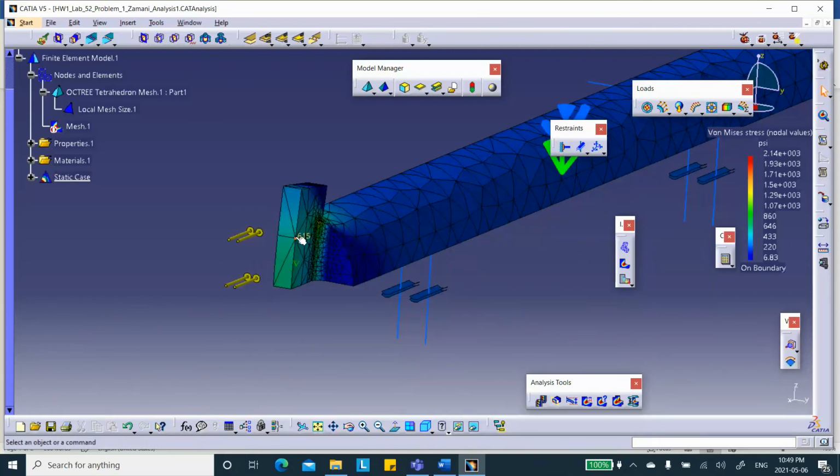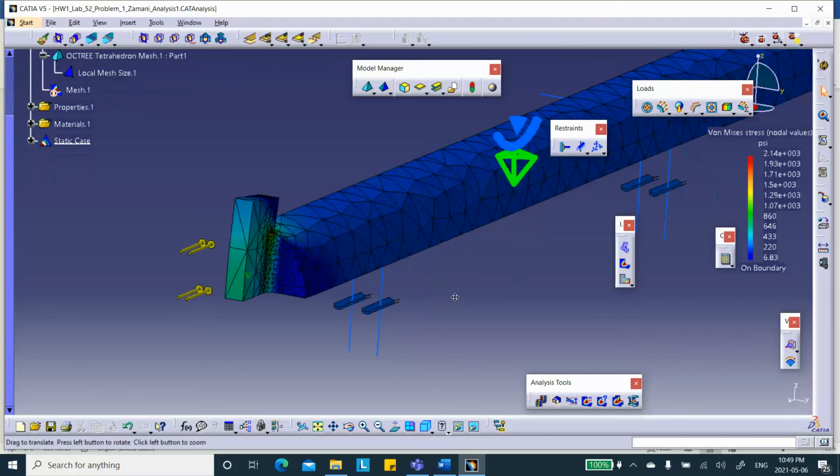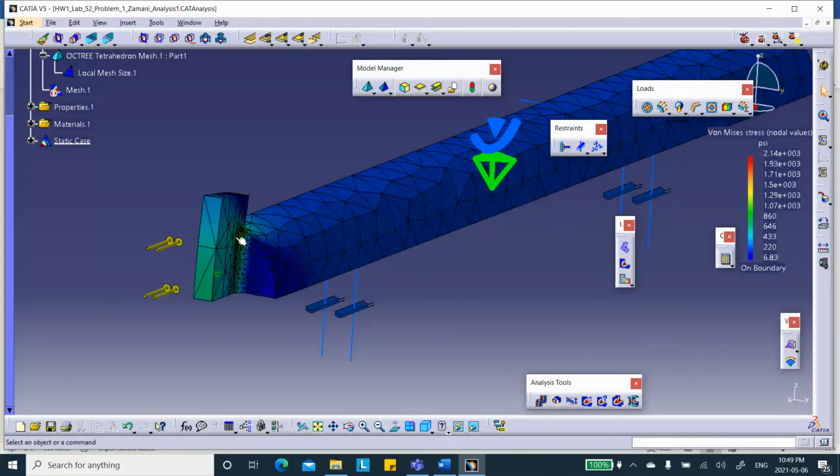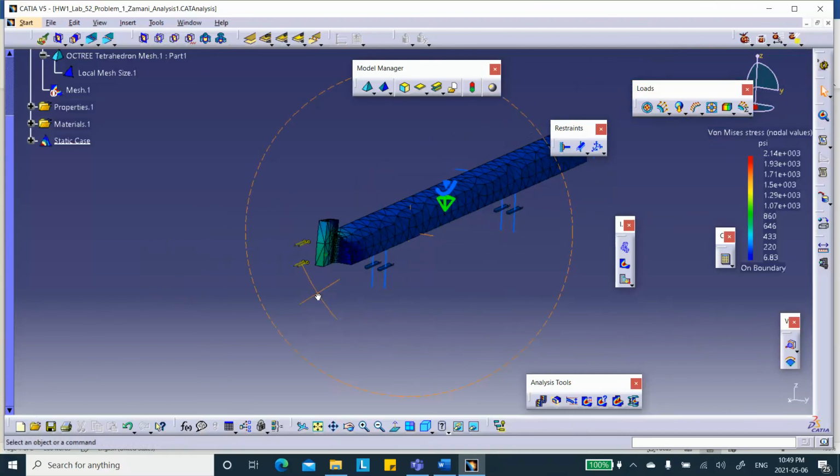But when you get close to this end, the stress has become large, and particularly in that corner, it becomes very large. Okay. Did I say 2000? I meant 241, 240 psi, somewhere down here in the blue area. 241. When you get down here, it gets large, and then of course this is 2104. This is a terrible mesh. I mean, basically, don't do this for designing a part. This is horrible mesh, horrible design.